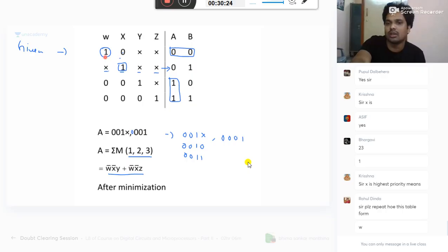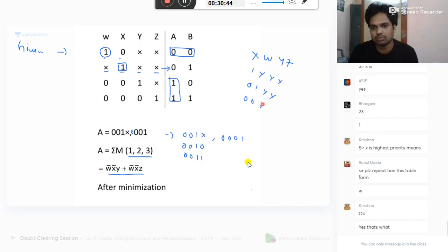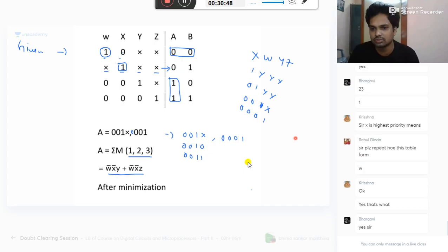If it is reverse, what is that? tPD2 is less than tPD1. Then you get 1, 0, because that fellow will change first. So what is the answer? 1, 0 or 0, 1, depending on your propagation delays. If equal, I told already that it will toggle between 0, 0 and 1, 1. It is not valid, but you get some kind of 0, 0, 1, 1 condition. So let's move.